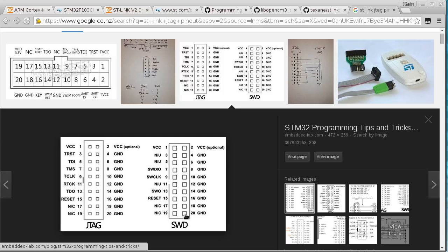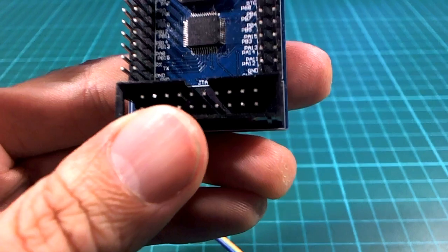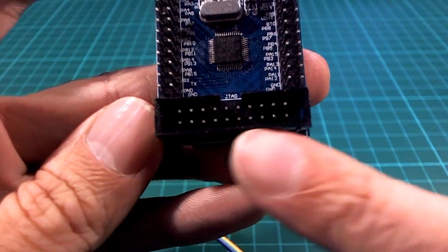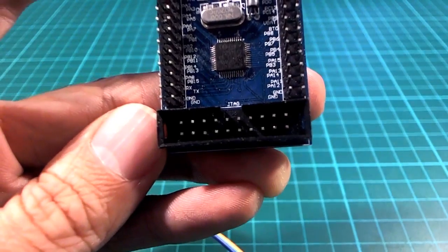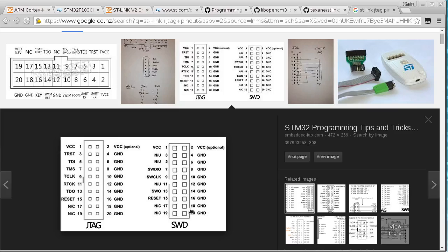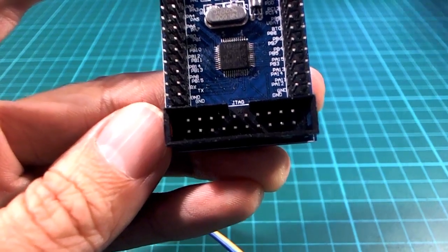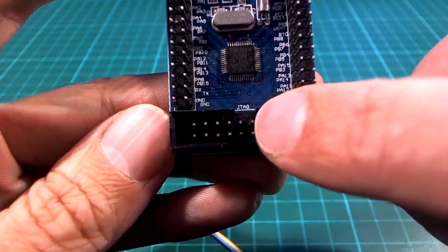Well, anyway, all of these pins along the side here, that is the back edge, except for the very last one. The bottom right corner is VCC. All the other ones along that edge are ground. So there's VCC there. And then the other 2 pins that we need are SWDIO and SW clock. Data IO, I guess that is. So those are the 2 pins just to the north of the center section, that's those pins there and there.